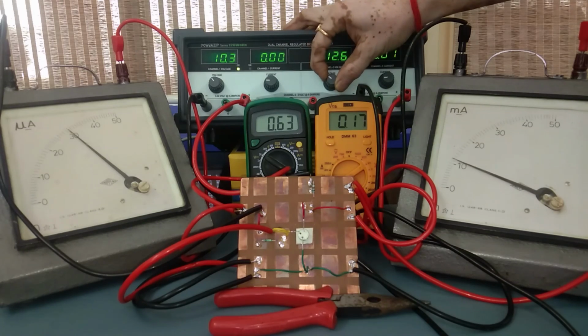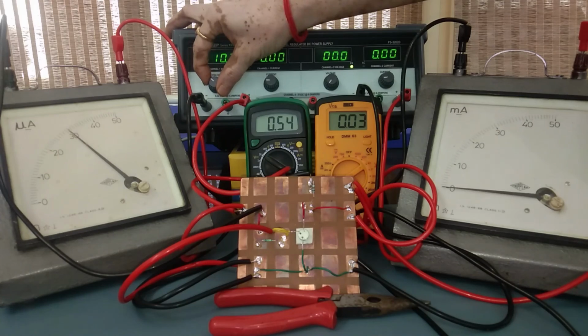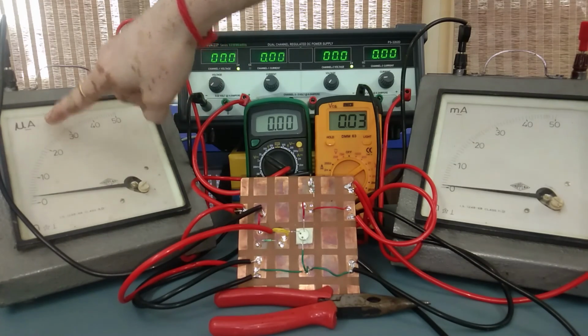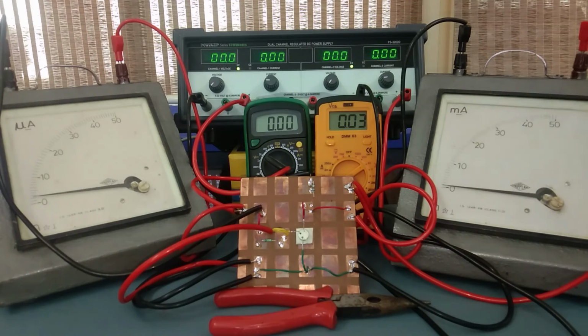This means that the transistor is working simply as an amplifier, because we know the particular relation beta DC is equal to collector current by base current. Now since beta DC is the forward current gain of the transistor, we can very easily confirm here that yes, for a very small value of base current we can get a larger value of collector current. See here that base current lies in microampere and the collector current is in milliampere. So that's all about this circuit.